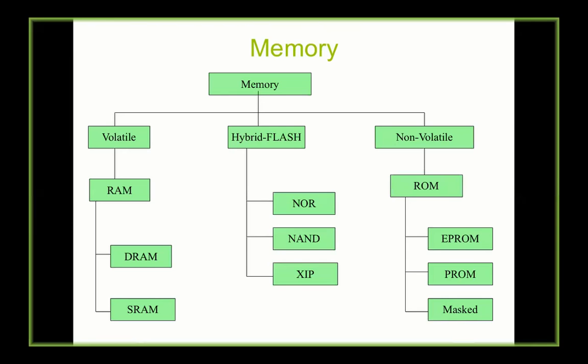So instead of you starting the program, then transferring all these contents to the RAM area, and then loading the application for execution, which may become a slowness or startup challenge. So there's a need for fast booting of an interactive application. So TI came with a logic called XIP flash. As I say, X means execute, I as in, and P as in place.